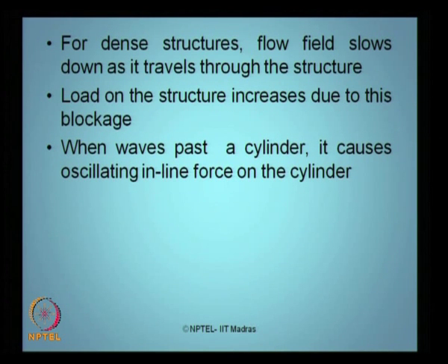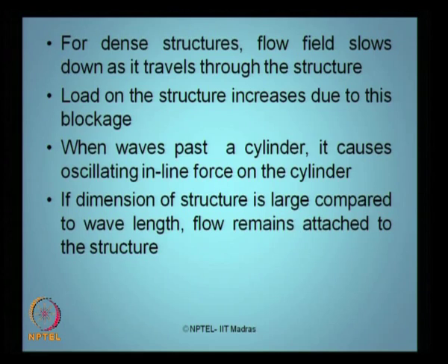When the wave passes the cylinder, it causes an oscillating inline force on the cylinder, which is very important from the vibration point of view. If the dimension of the structure is very large compared to the wavelength, the flow remains attached to the structure. So the assumption of flow not separating from the cylinder is very important only for large diameter structures, where the diameter is comparatively large with respect to the wavelength of the approaching wave.